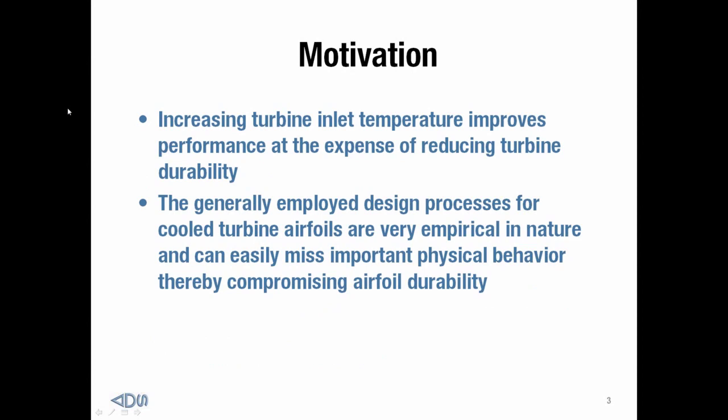Now, one of the conventional ways of accomplishing this, at least from a turbo machinery designer's perspective, is we want to increase the turbine inlet temperature. That way we can improve performance of the machine, but this does come at the cost of reducing the durability of the turbine.